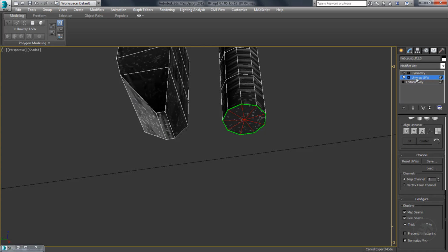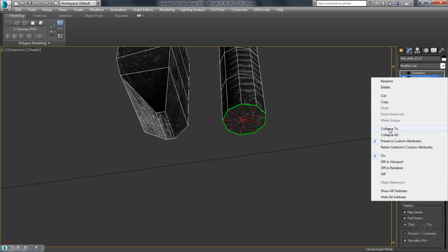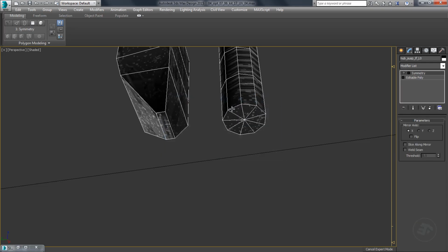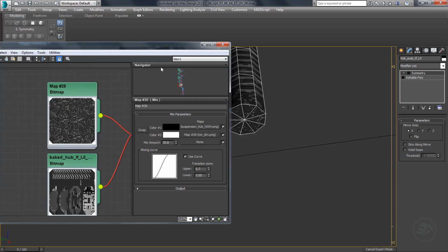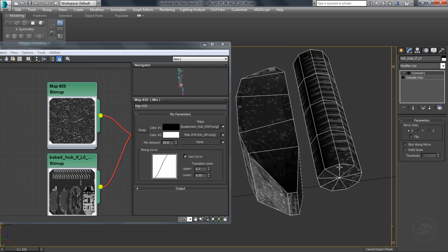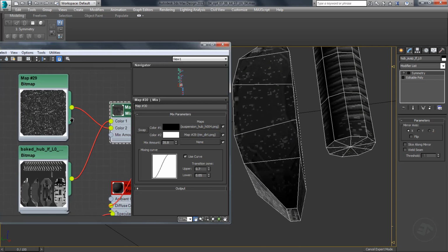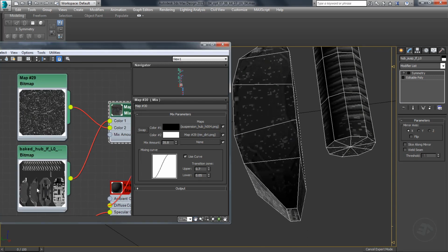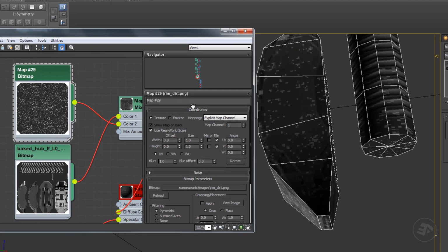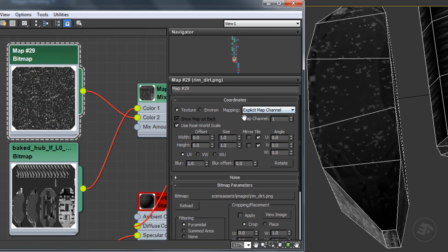Next, I will show you how to transfer the UV map between different channels, and also how to manipulate other channels UV individually. The viewport by default utilizes only channel UV1 to render the assigned materials of the 3D object. All the materials and the nodes that you will create inside the material editor are set to be rendered on channel UV1.